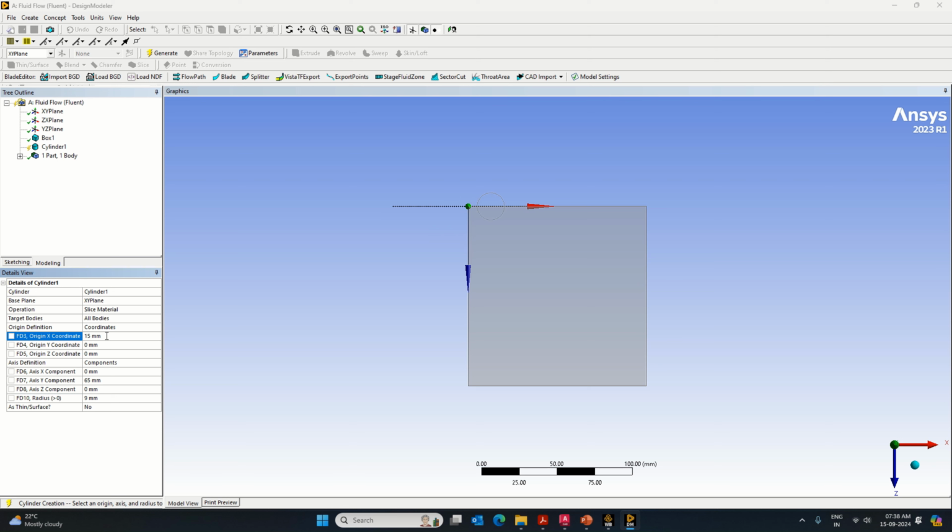Okay, so one more thing, let's go to the primitive. I will put cylinder. Instead of add metal, I will make it slice metal. X component I will put 15 as it is. Now the z component, I will add plus 23, so that is 74.5. So this will be the third location. Y component make it 65, z component equal to 0. So let's generate. So this is the third thing which I have generated.